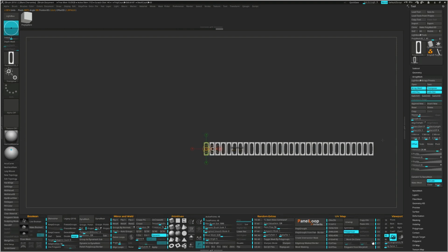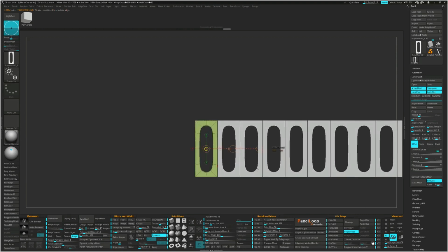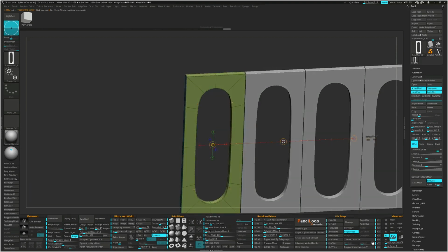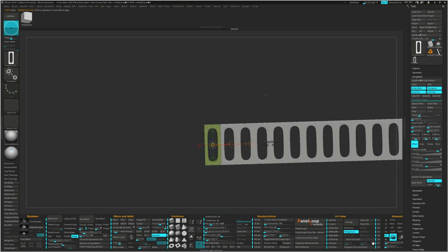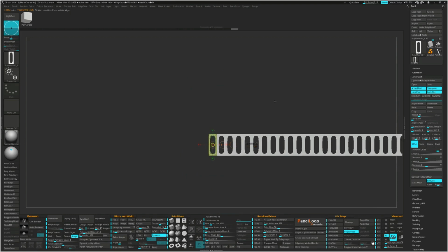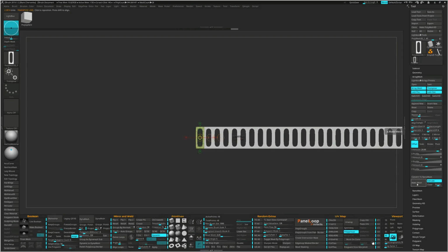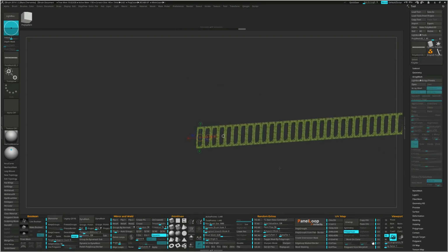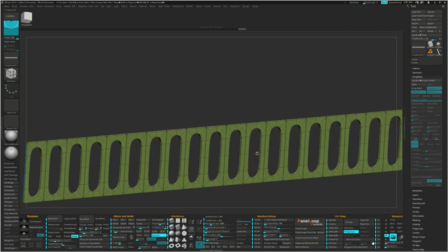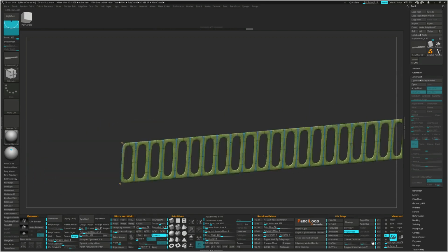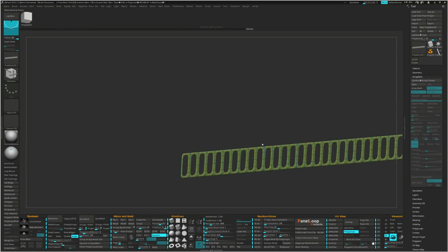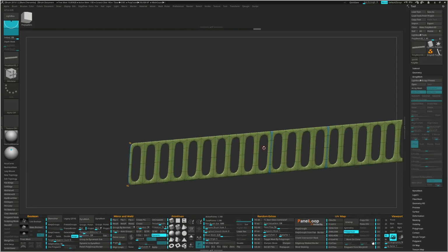Click inside the middle circle on the transpose line and move the instances out. Adjust the mesh until they are touching. Make sure Extrude is on and click Make Mesh. Turn on Dynamic and adjust the weld distance until all the verts from the array are merged.